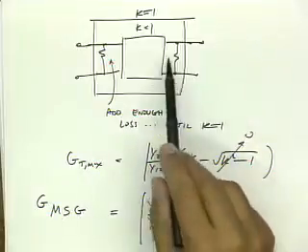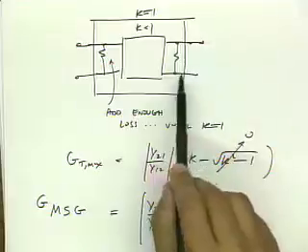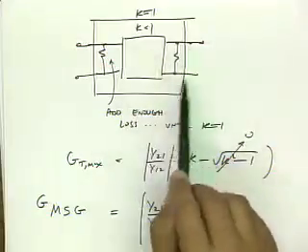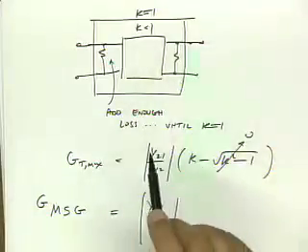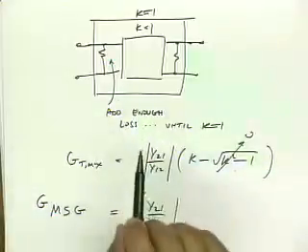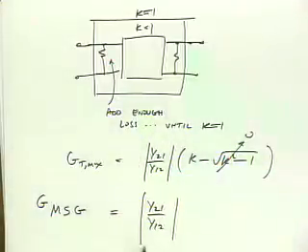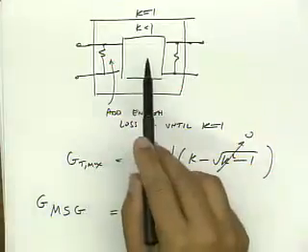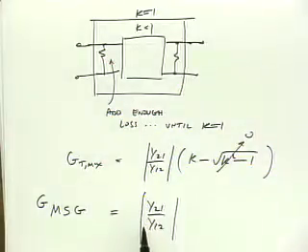The way to think about these loss terms is that I'm putting in enough resistance here to quench any oscillations that might occur otherwise. And now I have a nice stable two-port. So this is how I define the maximum gain for a device where K is less than 1. And the reason I like to define this is, nobody likes to work with infinity, right? What's infinity? So if I look at a particular device, let me take a transistor.